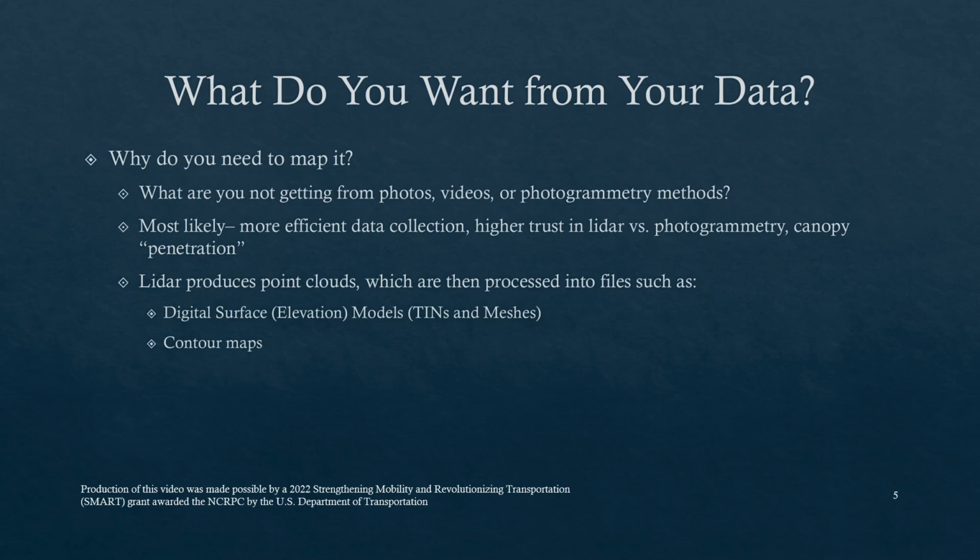But the most likely reason to use LiDAR is for that more efficient data collection. And sometimes there's just higher trust in LiDAR. Engineers and people used to working with this kind of data are more familiar with LiDAR than they are with photogrammetry, so there's just a higher inherent trust in the data. And sometimes that can be reason enough. And then there's this term around canopy penetration, which is really a misnomer. There's no such thing as true penetration.